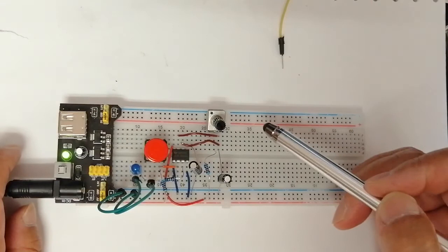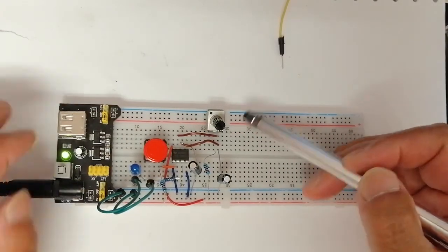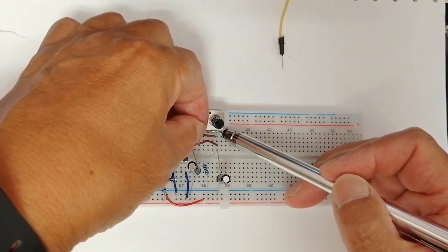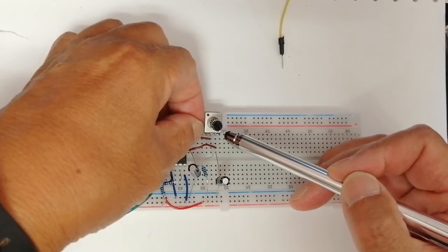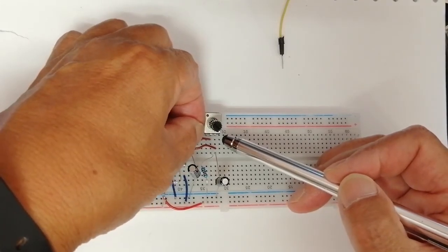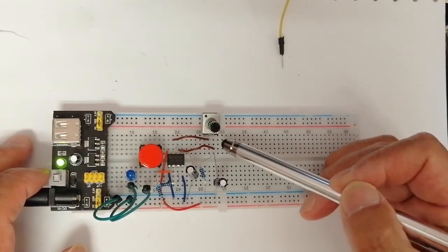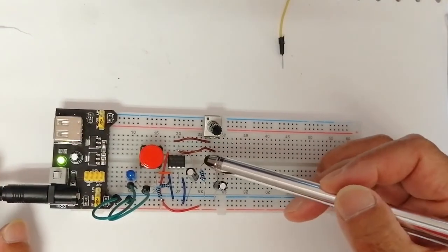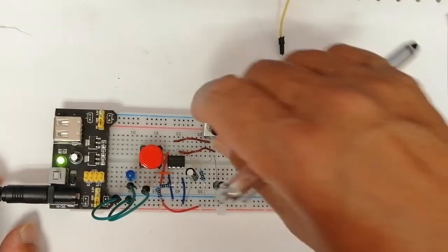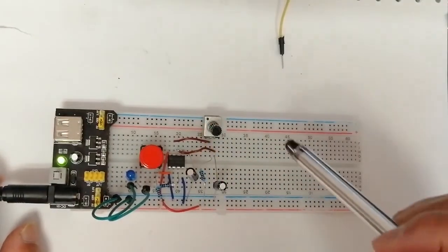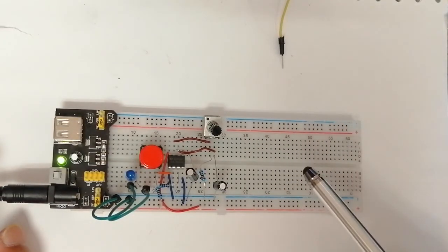Okay, now we do something more interesting. What we do is we move this guy into this. This is the discharge. We discharge between the resistors, so the discharge goes through this resistor. So instead of discharging suddenly, it's going to discharge gradually.